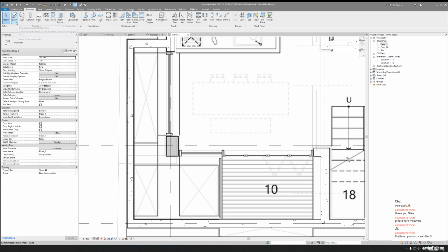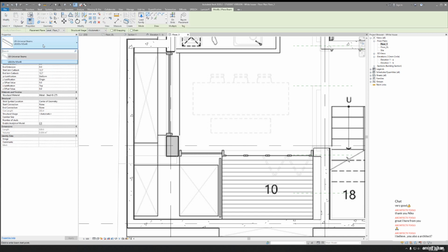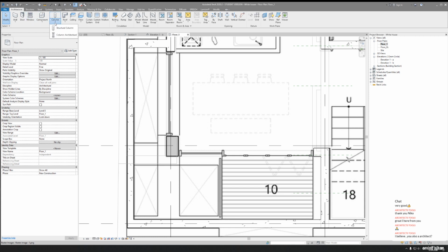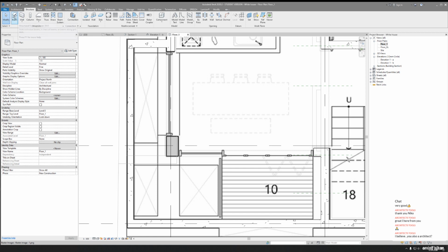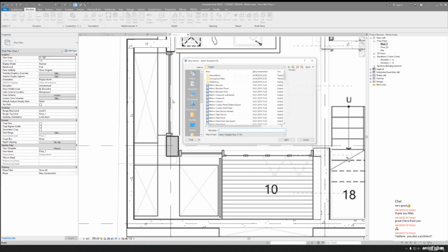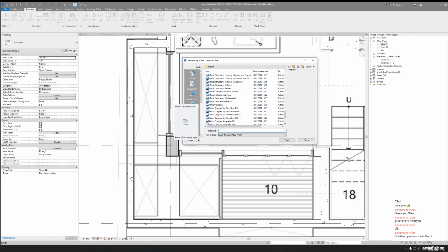Beam. Let's go to the beam, and we have only structural beam. We should create the beam actually. We have a lot of ways again how we can solve this problem. We can create the beam. We can use, for example, for this wall, a structural wall, I mean. But I think it's better to create the beam. Let's create the beam. We need to go to File, New, Family, and let's create the beam. Here we need the metric structure.